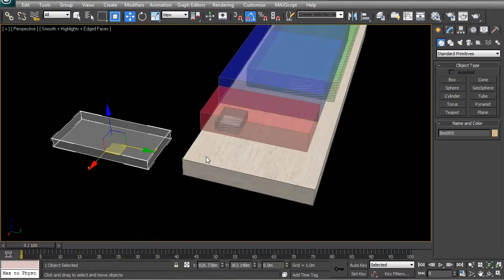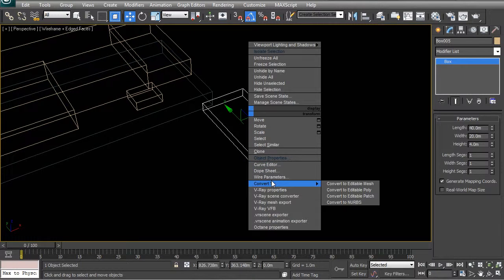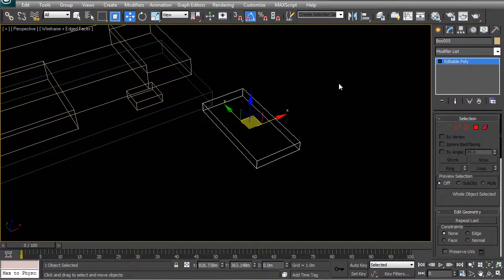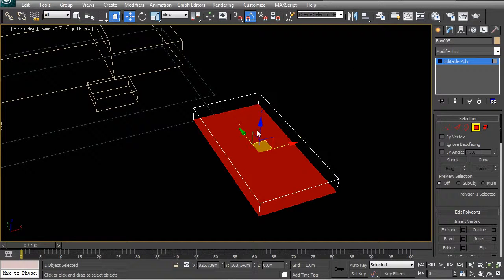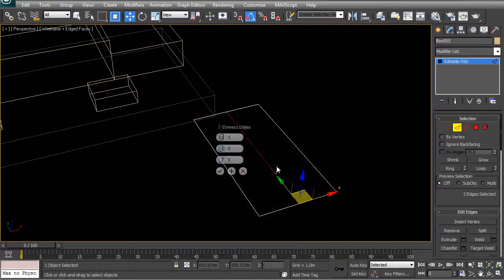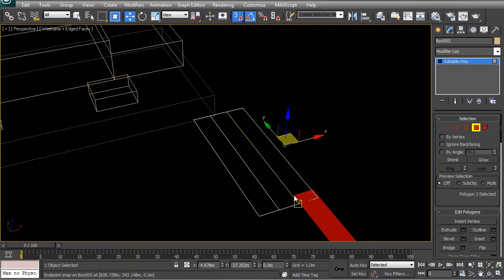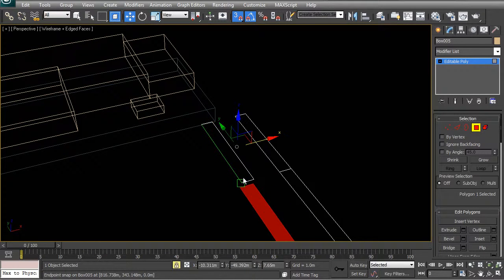Then this back of house space, what we can do here is let's go and divide it in two. So I'm going to right click and go to convert to editable poly. Instead of using the figure of 4 meters in terms of the height, I'm only going to use the bottom. I'm going to invert that selection, delete everything, and here I'm going to start cutting up this object. I'm going to cut it up into 4 objects, right click and split those, so that I can now start to create a new type of object with that same area.